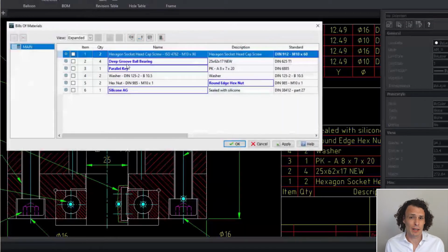Now let's take a look at our BOM feature. By default, a main BOM exists which contains information about all the parts and assemblies in a drawing. A drawing can also have multiple BOMs. You can manage BOMs and BOM data defined in the drawing in the Bill of Materials dialog box. There are functions such as append column, remove column, add items, insert items, remove overrides, and create part lists in the current BOM available in the dialog box.